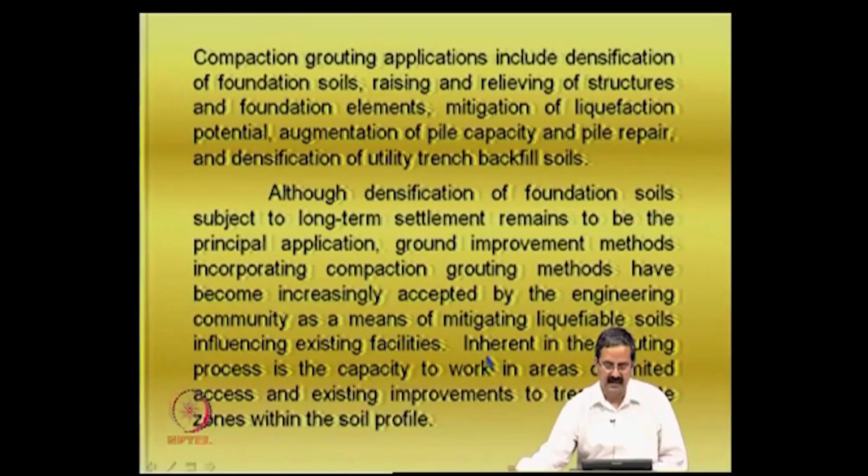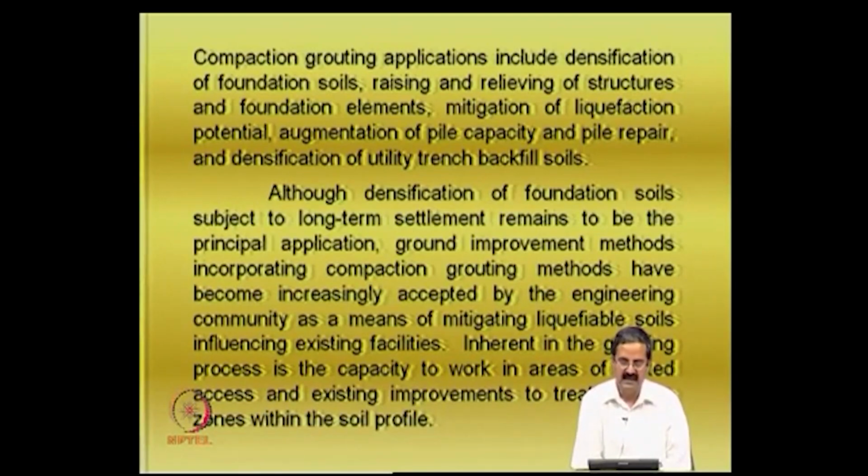Another advantage inherent in the grouting process is the capacity to work in areas of limited access. Say for example, there are some places where you do not have access, like how do you construct a certain approach to do a certain repair job. When you want to do a repair job, an approach for that particular location is also quite important, and it is possible that with grouting you can make corrections in places where there is limited access as well, which is a very useful advantage in many cases, for example many urban areas.